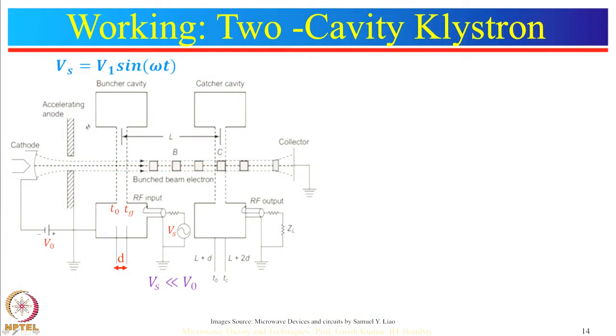So, after passing through the second cavity, all the electrons will give up their kinetic energy to the microwave fields present in the second cavity, and because of that their velocity will be reduced and they will be collected by the collector. Now, see its working in more detail.